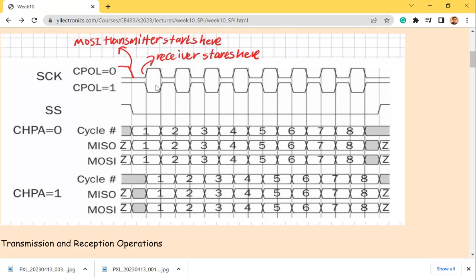So both are SCKs, depending on which one you are choosing, depending on how you code up your Verilog. And for MOSI, when this one is 0, we are picking 0 and 0, right? So SCK is the top one, and we are using this mode instead of the bottom one. So you don't have to worry about the bottom one for now.